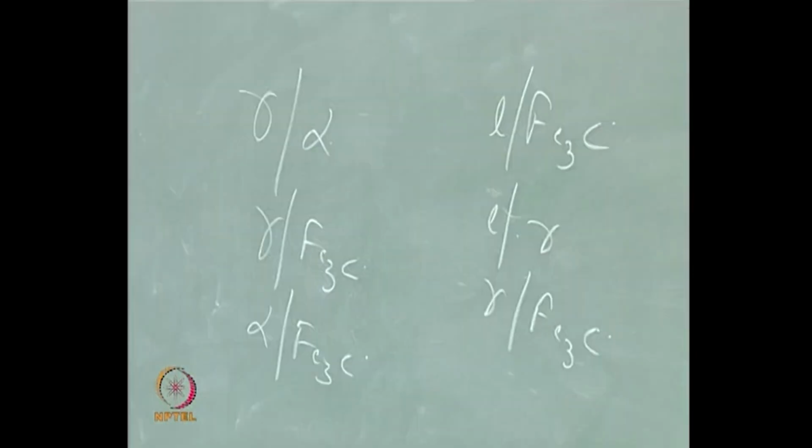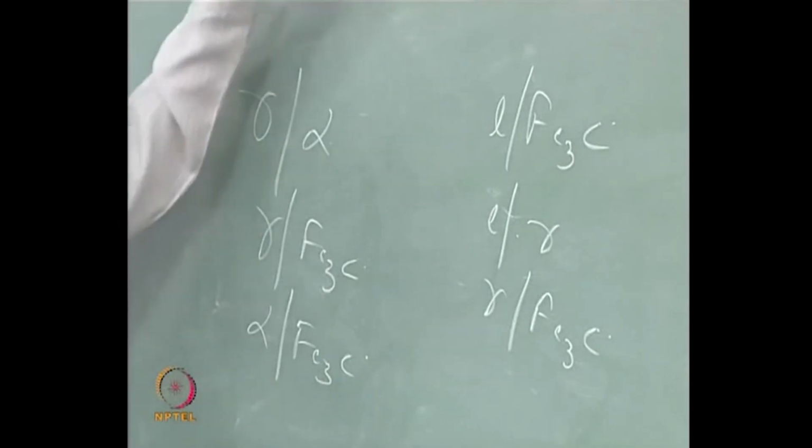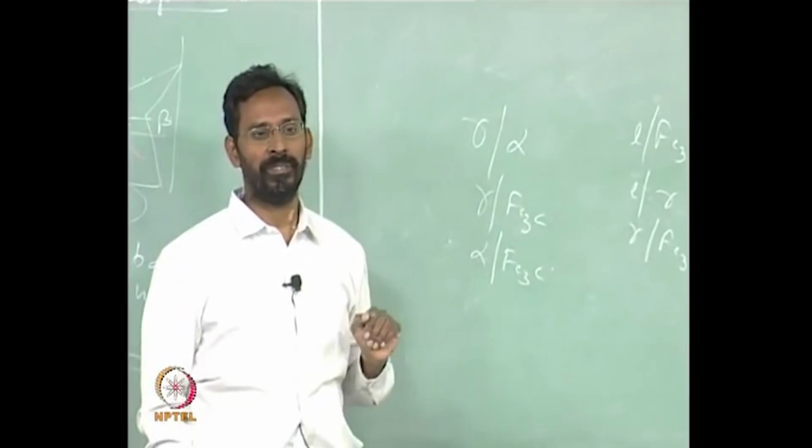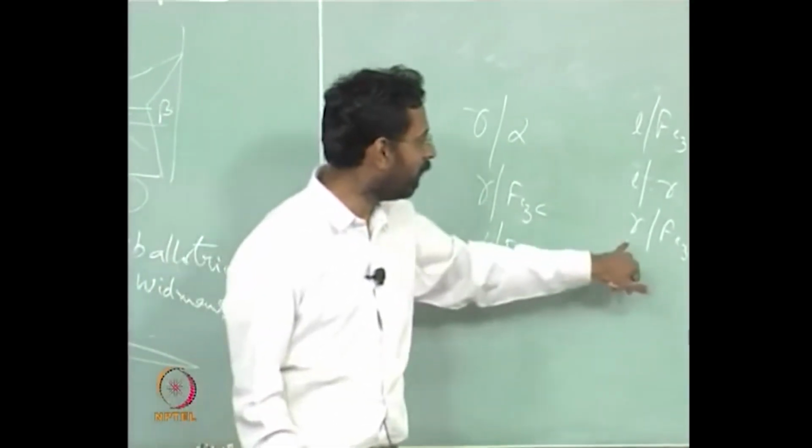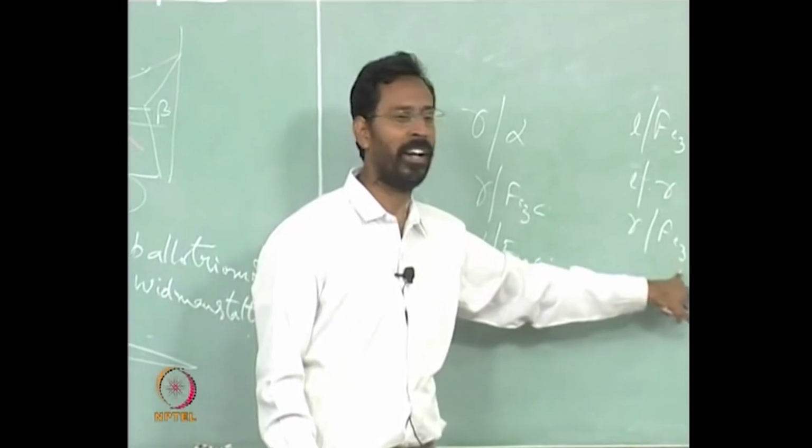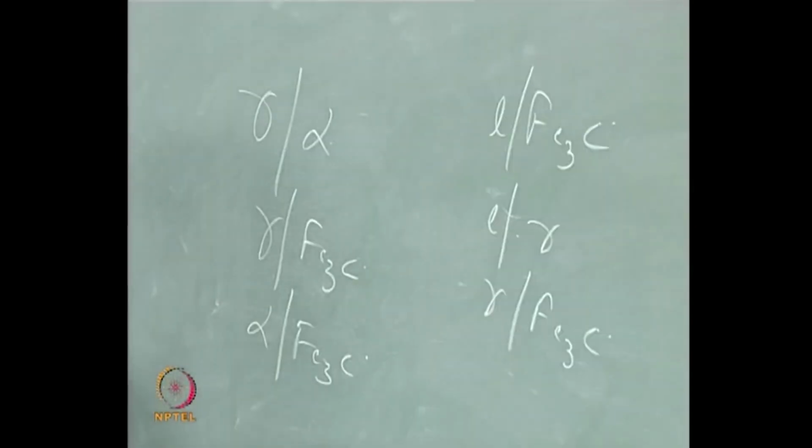A tetragonal structure has a correlation with a cubic structure, excepting the C axis, everything else is similar. In fact you take a cubic, pull it, and that is how you get a tetragonal structure. So that is how there is a possibility of an alpha theta lamellar eutectic coming. Whereas here you cannot get a lamellar eutectic because gamma and orthorhombic have no correlation, and the compositions are also entirely different. As a result you will not see a possibility of a lamellar there.